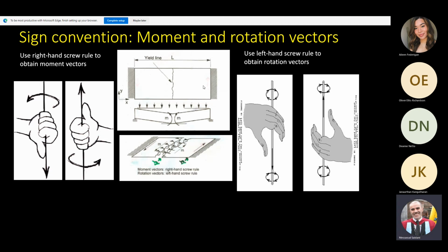a one-way slab, and I'm going to explain for this slab. So this is your slab, okay? Simply supported on two edges, right? And it's going to fail in the middle here. So when the slab fails like this, what happened to this side here? This is what you see in a cross section. This is how the slab fails, right?